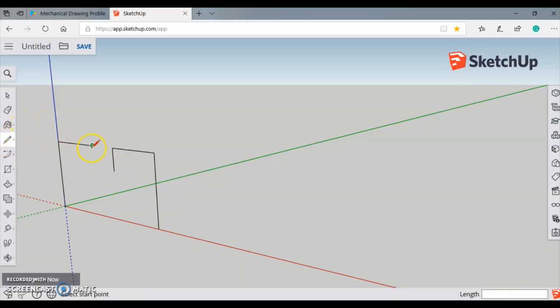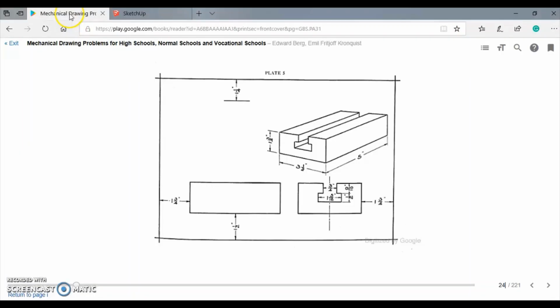Again, I go over to the other side to do the same thing. It automatically goes 9/16. The next thing we're going to do is figure out this distance and this distance. Now, half of 1 5/16 is 21/32. Half of 3/4 is 3/8, or 12/32. So it means there is 9/32 is the distance for this, and then it's a 1/2 inch tall.